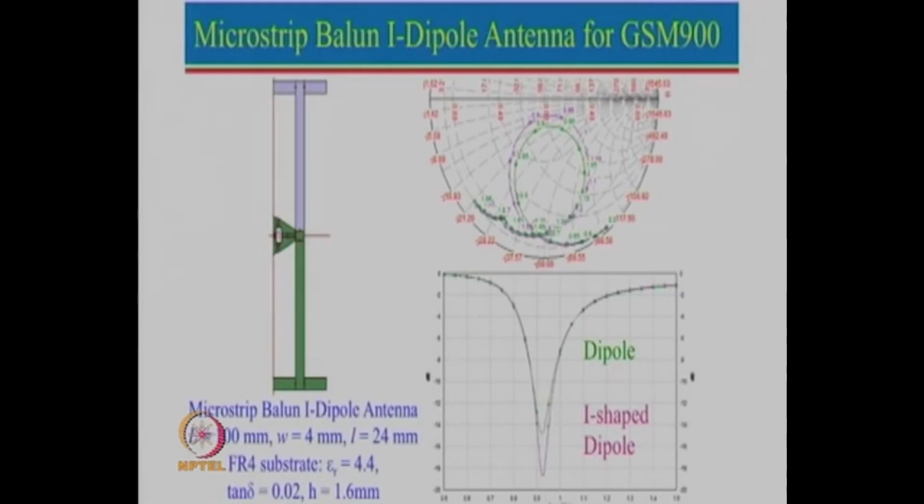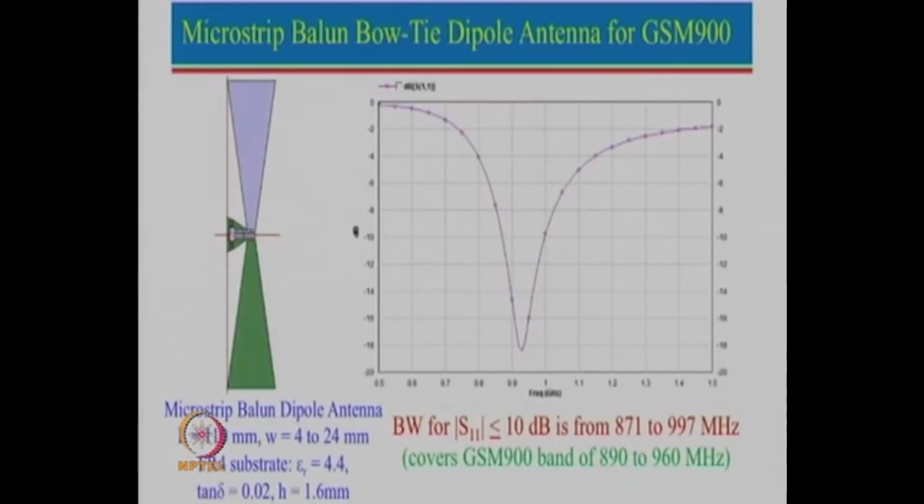Now bandwidth can be increased further also. As I had mentioned, one can use a conical dipole antenna, but here instead of a conical dipole, we have just used more of a triangular dipole. Over here also the total vertical length is now smaller, because instead of 127 it is about 110. The reason the length is reduced is that it is not only the vertical length that is important; current will flow in the outer region here. So it is the slant length which is more important compared to just the vertical length. And by doing this, we also got a little more bandwidth.